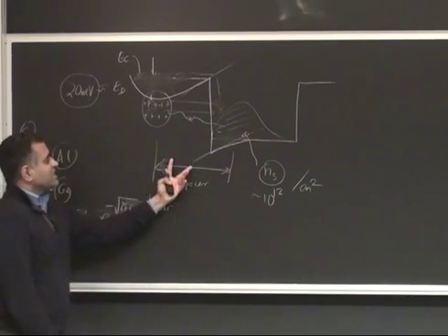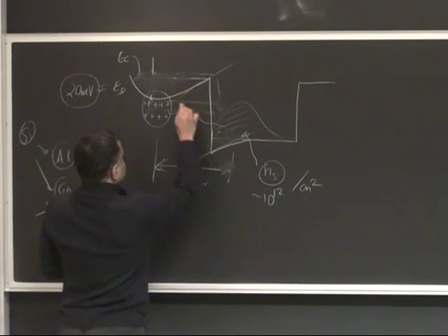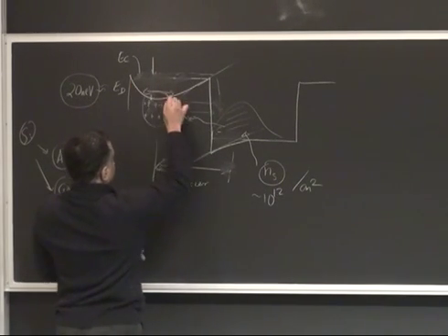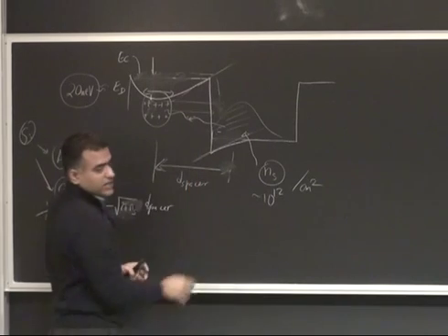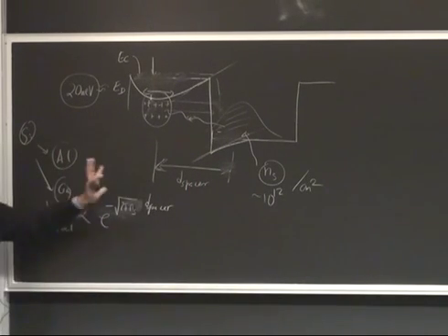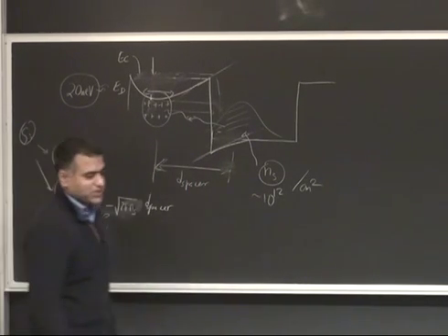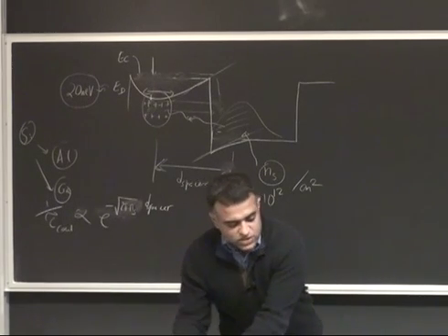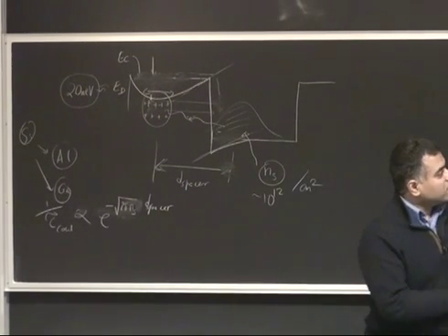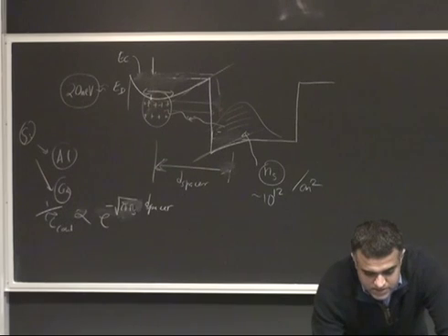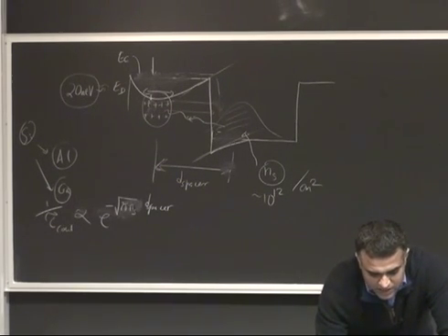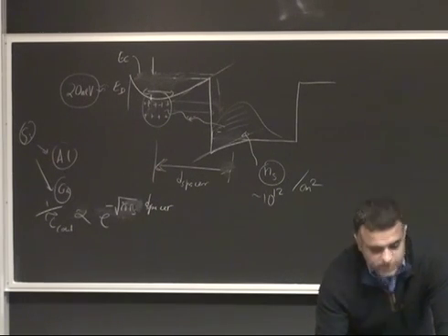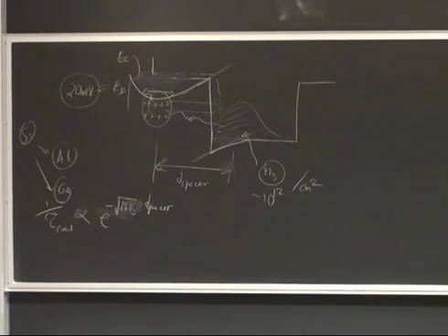So you can see these thicknesses, the barrier thickness, the doping, how thick a layer you put the dopants in. All these are very critical because they determine very accurately what happens here. So what we can do is put dopants in this layer, and that's the reason I've broken this up. We had a total of 100 angstroms of 30% AlGaN here, but I've broken it up into, say, 20, 50, and 30 now.